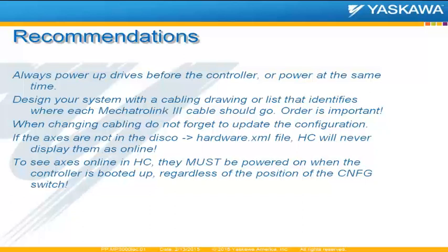Sure, this may be the case where there's more confusion potentially in a commissioning situation, especially if the controller is on a separate power supply, a 24-volt power supply, and the servo packs are being powered separately. There may be some additional timing consideration during commissioning where this may be important to remember.